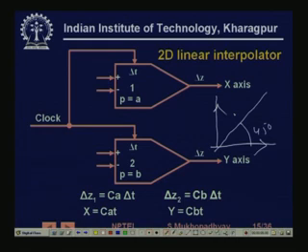On the other hand, if you are moving along this axis, then there has to be more velocity along y axis and less along x axis, right. They are related by the orientation of the line that you want to cut. And the slope is determined by what? Determined by how frequently the delta z commands are given along that axis. So it depends on how frequently an overflow is going to occur.